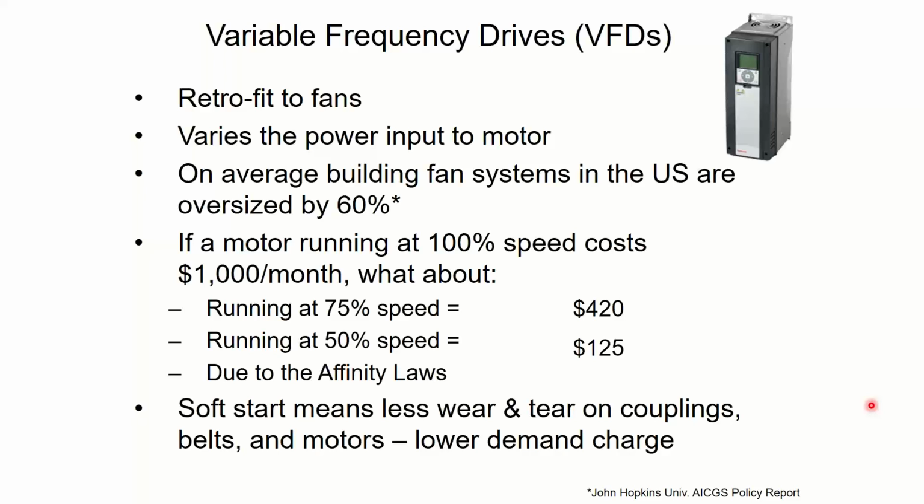The other nice thing about these VFDs, other than the energy savings, is the fact that when you first turn them on, they don't apply all the power immediately. A normal unit would do that. It would apply all the power immediately. It would have a lot of stress on the belts and the motor, and you would hear the loud booming noise and the ductwork expanding and all that stuff. That's not how a VFD works. A VFD goes up slowly.